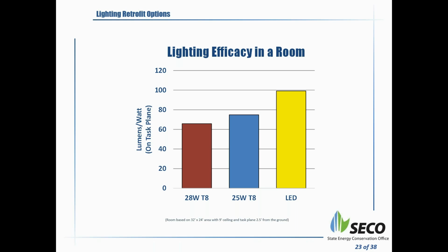One very important thing to keep in mind is that the lumen output in an LED fixture or a lamp is all dependent on the type of the drivers. That's very important. This is different from when you used to have ballasts. You can specify different types of drivers that will drive the lamps to produce a certain lumen output. And normally there's a cost difference between going from one ballast to the next, or from one fixture to the next, so there are a lot of options.